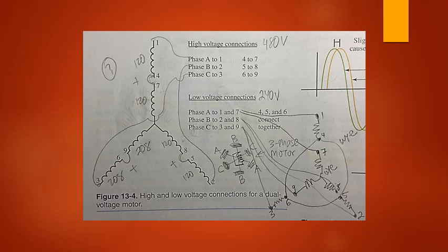Slip. Remember, rotor current is dependent upon the stator. As the rotor turns inside of the stator housing, the rotor bars cut the magnetic field of the stator. The action of the rotor bars cutting the magnetic field produces a heavy current. If the rotor catches up to the synchronous speed of the magnetic field in the stator, the rotor bars would not cut across the magnetic field.